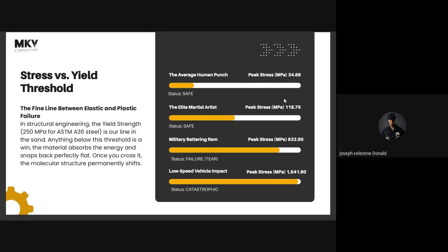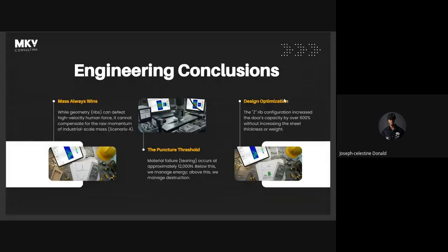Even at that, you start thinking, okay, next is factor of safety. Next is where exactly is this failing from? So you don't go randomly optimizing everywhere, adding stuff you don't need. You start thinking about cost, and about where specifically we are having this maximum stress from using your probe, and then we can say, okay, this is where it actually comes from.